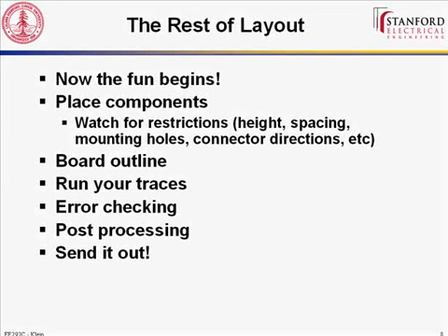Yeah? I've heard that right angle traces, if you're not doing a professional kind of board, can flake off. All right, so the comment is that you've heard that some lower grade PC boards will have right angles flake off. From my own experience, I haven't had problems with corners in particular flaking, but if you have a crappy board, just everything flakes because it's laminated down.